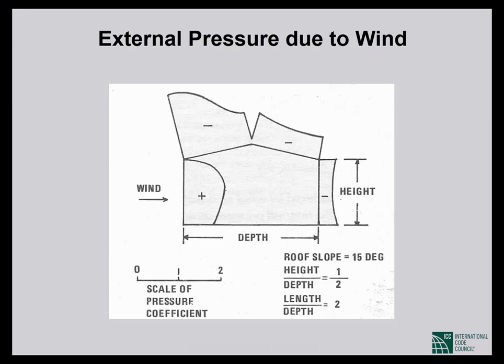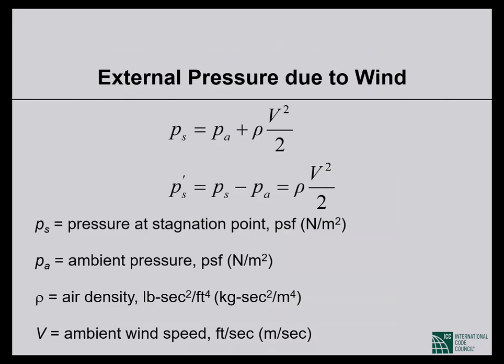This sounds very basic, but I have seen buildings on the island of Kauai, in Hawaii, where after a hurricane, a building was several feet away from what it used to be before the hurricane, because there are no anchor bolts securing the building to the foundation. The building has flown. So the roof has to be secured to the building, and the building has to be secured to the foundation. Things that basic have to be paid attention to.